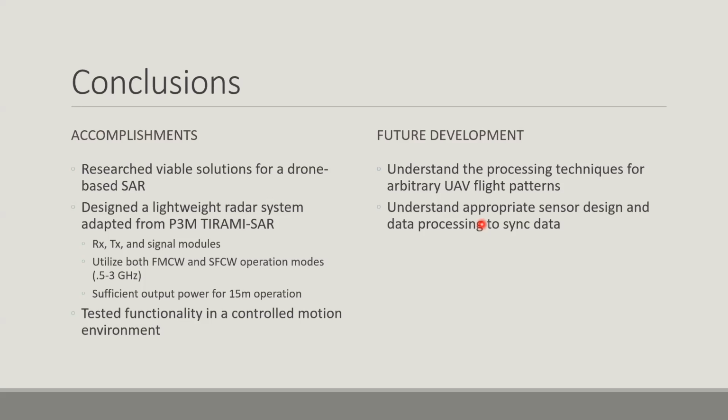So really all they did in this paper was create a proof of concept ground model adapted from a well-researched ground vehicle-based P3M SAR. And so moving forward, there's a couple things that need to be done to complete the drone system. First of all, there needs to be a better understanding of the processing techniques for arbitrary UAV flight patterns. Precise knowledge of this flight path is needed for proper compensation in the SAR processing later on.